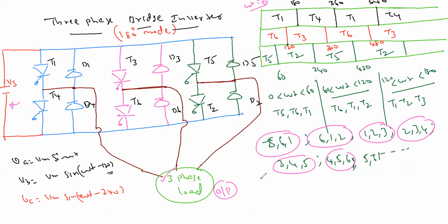Look at the waveform. A phase is here, VA, and VB phase. Where will B phase come? After 120 degrees. This is our B phase. Therefore I trigger the corresponding SCR, T3, after 120. Look here now, I trigger after 120, so your B phase voltage comes. But T3 T4 must complete 360, equally divided 180 180. So T3 at 180, 120 plus 180, T6 will go at 180. The work is done.